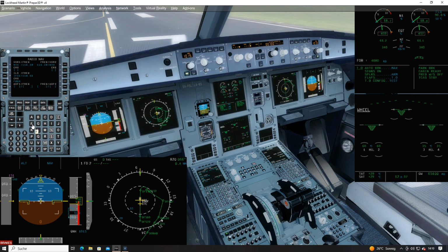However, we take the Frankfurt VOR station, which is coded by the letters FFM and entered in the top left side here. There are actually 2 VOR stations with the coding FFM. So we take the top one with 4 nautical miles distance, not the other one with 4,193 miles different distance, which is somewhere west, probably in the US.